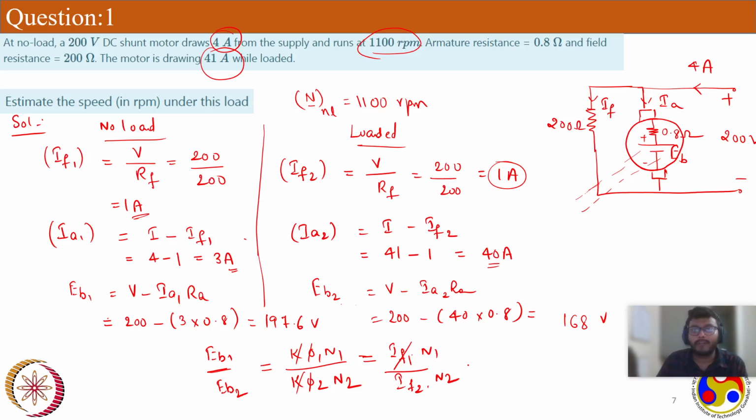Now, if you have understood that, the second sub part of the question is we have to estimate the load torque or shaft torque. We already discussed the shaft power and load power. If you divide that shaft power or load power by the speed of the machine, you will get the shaft torque or load torque. That's not a problem. Now, this torque and power calculation will involve our losses discussion.